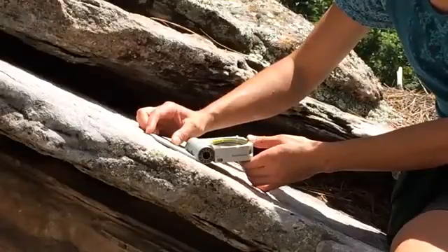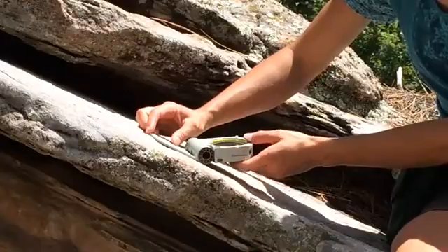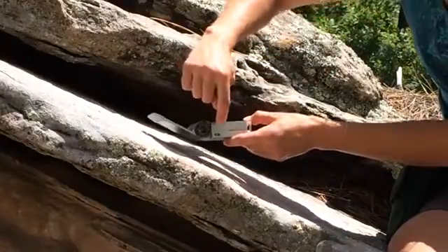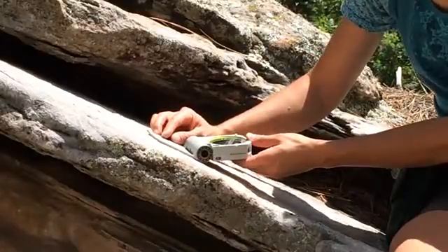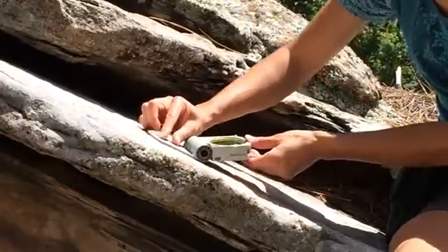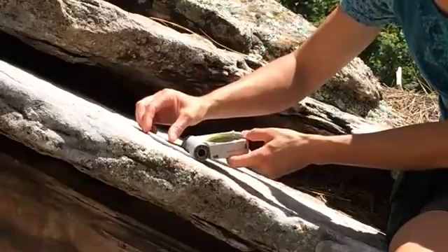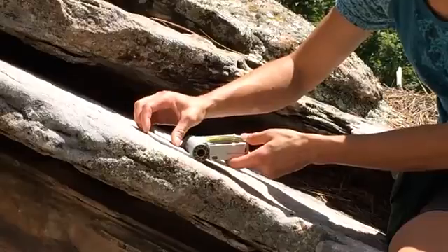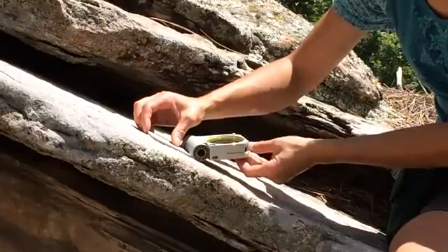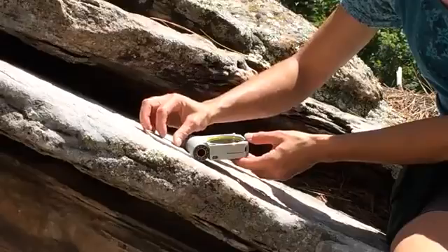So with the lid against the measurement plane, the next step is to level the compass face using the round bullseye level or the side vial levels if the top of the compass face isn't visible. Leveling the compass face will involve rotation around the major axis and also swiveling the lid on the measurement surface itself until a level compass face is achieved. Make sure that the hinge is only rotating around its major axis. For strike and dip measurements, the minor axis should be locked in its 0-degree position.